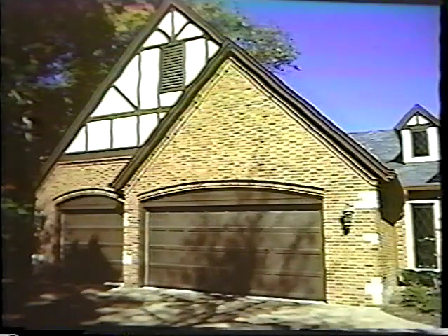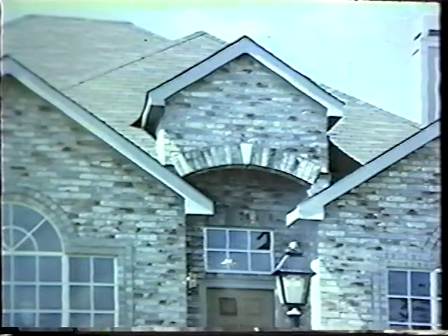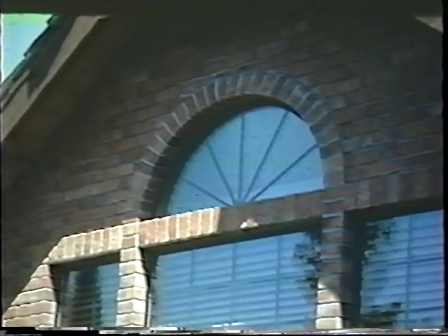However, today's arches are usually only one wythe thick and are often supported by slender columns. Problems have arisen where improperly supported arches have collapsed. Other critical elements are flashing and construction of the arch. Arches work if designed and constructed properly. Many different forms of arches are available: jack arches, segmental arches, semicircular arches, and other miscellaneous types.